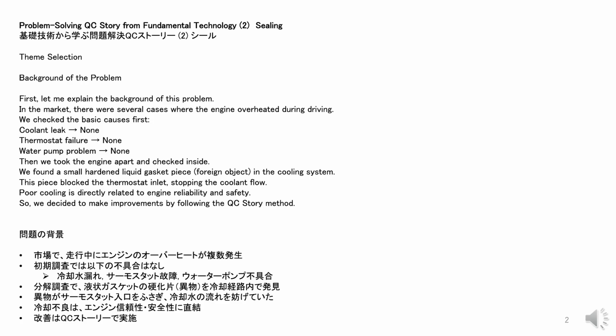We found a small hardened liquid gasket piece, a foreign object, in the cooling system. This piece blocked the thermostat inlet, stopping the coolant flow. Poor cooling is directly related to engine reliability and safety. So, we decided to make improvements by following the QC story method.